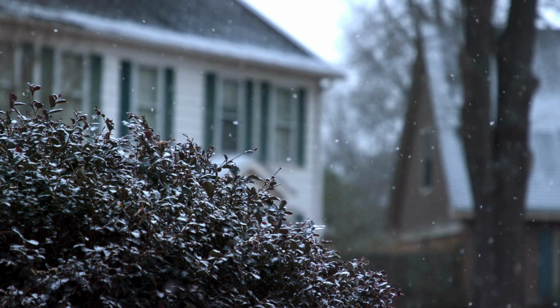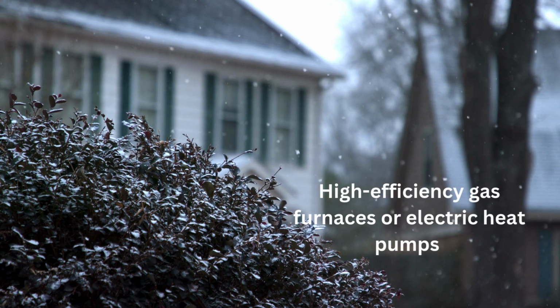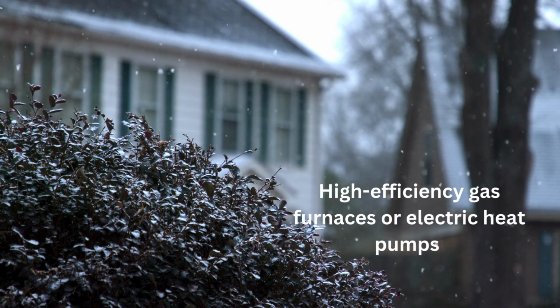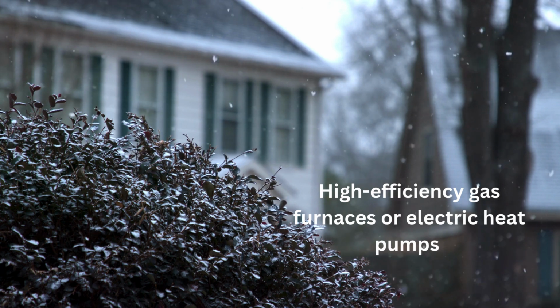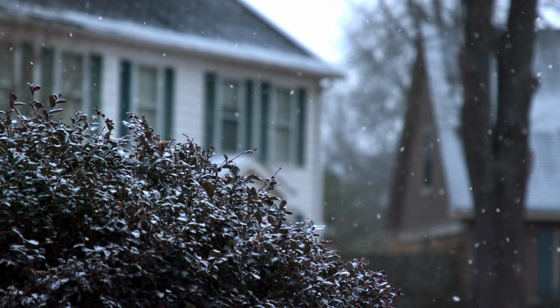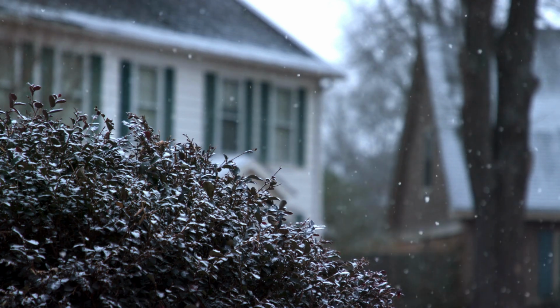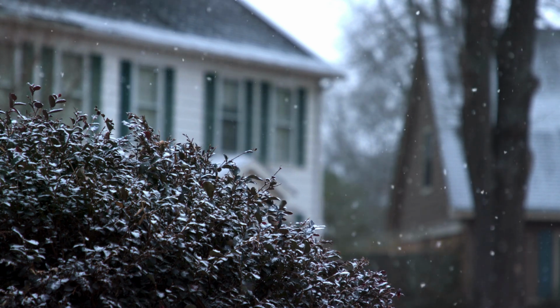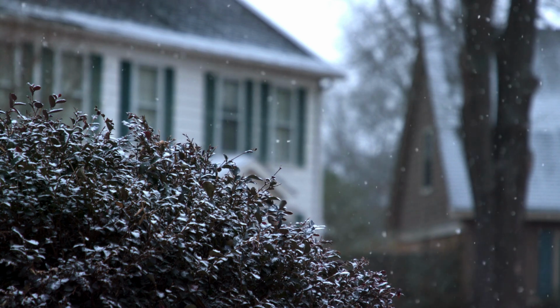snow is common, whereas the summers are fairly short and mild. High-efficiency gas furnaces or electric heat pumps designed for cold weather need to be efficient and powerful to handle the long winters. Heat pumps very often would require additional electric heat strip heating for when they have to run their defrost cycle. Cooling systems are less critical, but still can be necessary for the occasional summer heat.